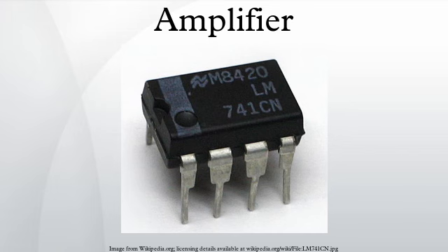By reducing the duty cycle below 0.5, the output amplitude can be modulated. The voltage square waveform degrades, but any overheating is compensated by the lower overall power flowing. Any load mismatch behind the filter can only act on the first harmonic current waveform. Clearly only a purely resistive load makes sense, then the lower the resistance, the higher the current.